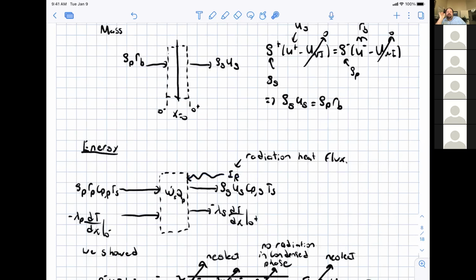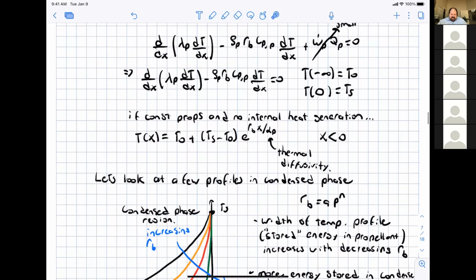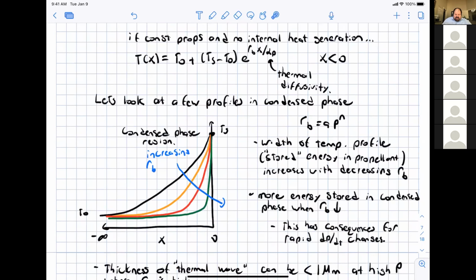And the reason that if you increase the surface temperature, according to this expression here, the burning rate slows down, is that if you look at the temperature profile in the condensed phase, if say the surface temperature is way down here, the propellant will be predicted to burn faster because it's going to take a lot less energy that needs to be absorbed by the propellant to raise it from its initial temperature to the surface temperature that allows it to stably burn.